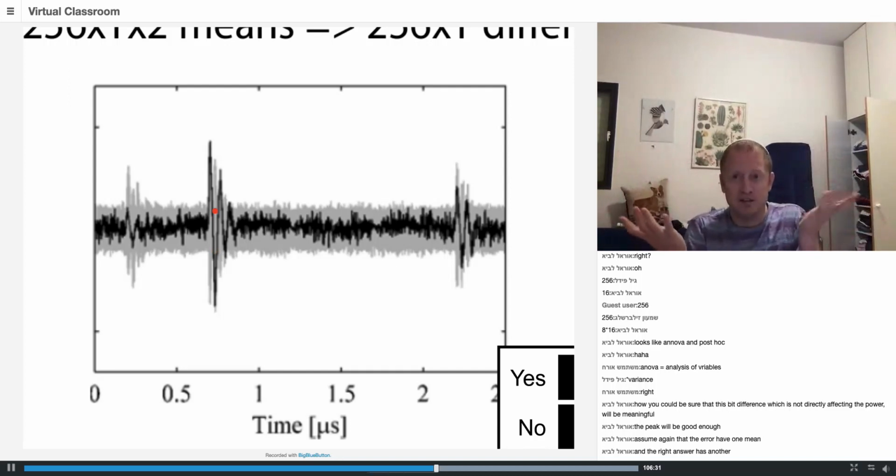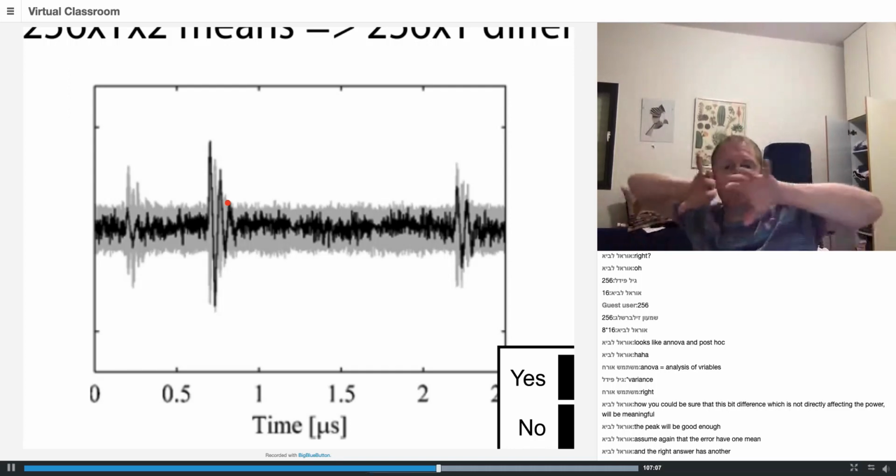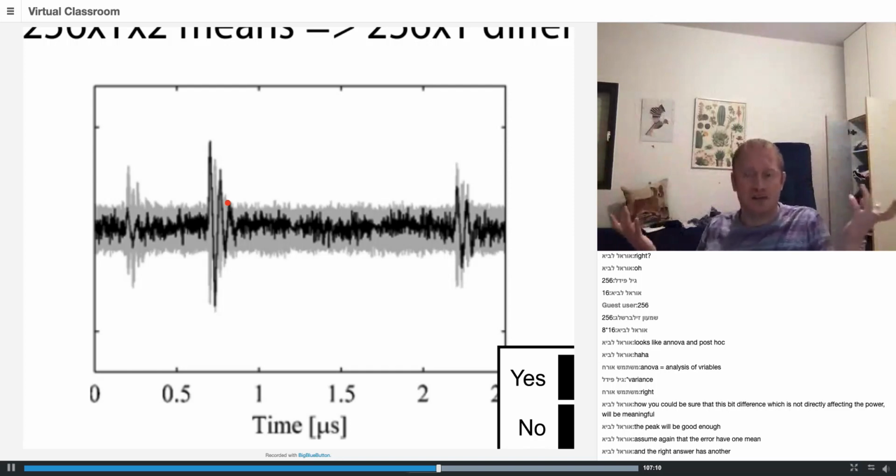What is the meaning of this? It means that this is the correct time. During this time in the computation, the device under test was indeed processing this state bit, the state byte. It was indeed processing the bit which we guessed, and we guessed it correctly. And this means that in this specific time, we got a peak. So this means this is the correct key. All the other keys, we didn't get a good split because we were dividing our measurement into two sets, which were essentially the same set.